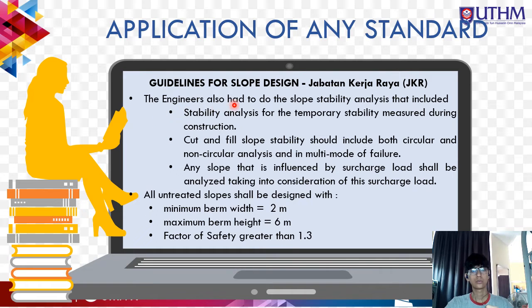The engineers also have to do the slope stability analysis, which includes stability analysis for the temporary stability measures during construction. Second, cut and fill slope stability should include both circular and non-circular analysis and multi-mode of failure. And last one, any slope that is influenced by a surcharge load should be analyzed by taking into consideration the surcharge load. Other than that, all untreated slopes should be designed with a maximum berm width of 2 meters, maximum berm height of 6 meters, and a factor of safety greater than 1.3.